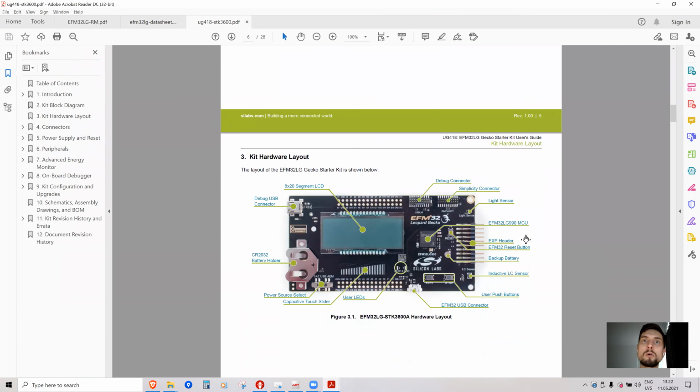Let's see, is it somewhere here? I think this piece. On newer development kits and on older development kits, there's also this part, an external low frequency oscillator, and those are much more precise devices. So if you have some extra money, you should put it. It costs something like 30 cents, maybe even cheaper. And if you add it to your processor, you get a more precise result. So in our development kits, it's soldered on.